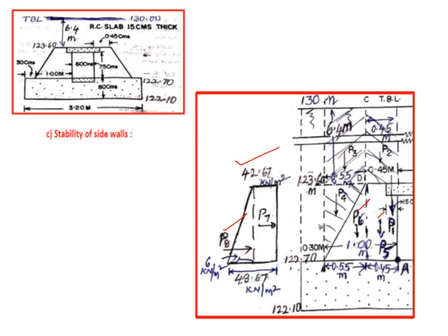So now the moment is calculated about this point. So each of the lever arms you should calculate. For example P1, because the bearing is 30, so it is 0.15. Similarly for P5, this is 0.45, it is 0.45 by 2. What about P6? It is 0.45 plus one third of 0.55, like this. What is P2? For P2 lever arm is 0.45 by 2. What is lever arm for P3? It is 0.45 plus half of 0.55.